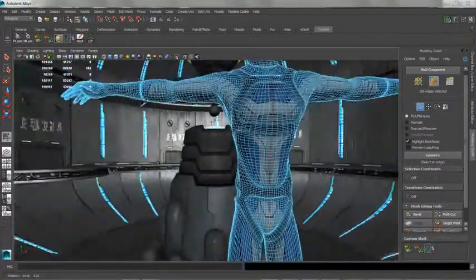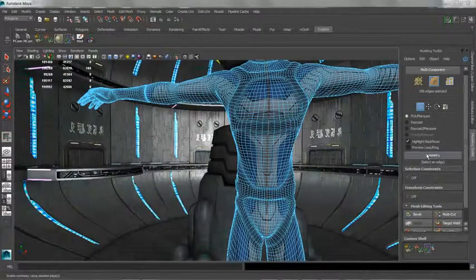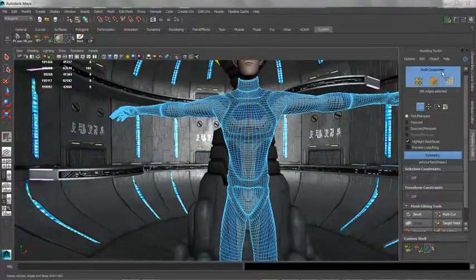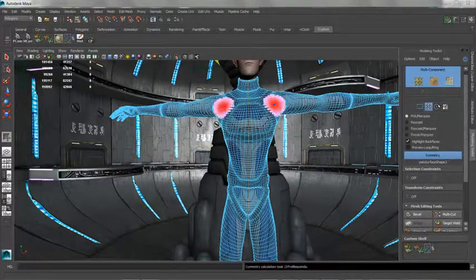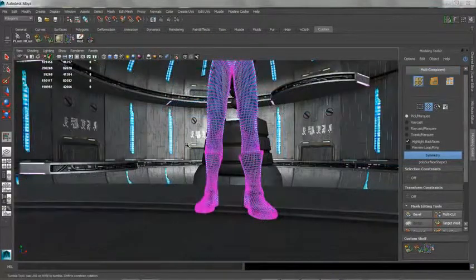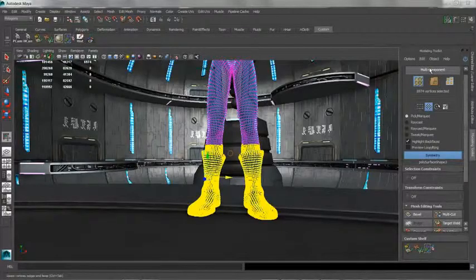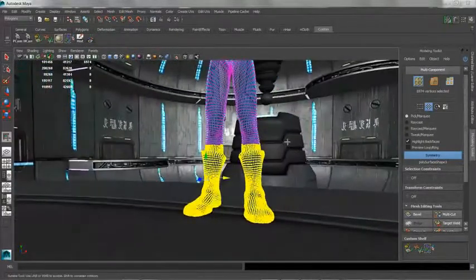In your scene, select an edge on your polygon mesh to define the line of symmetry. This allows symmetrical modeling across meshes, even when posed. Any selection you make is highlighted in blue and is applied to both sides of the mesh. Symmetrize copies the selected mesh topology across the axis of symmetry. Simply select components on the side of the mesh you want as a target and click Symmetrize.